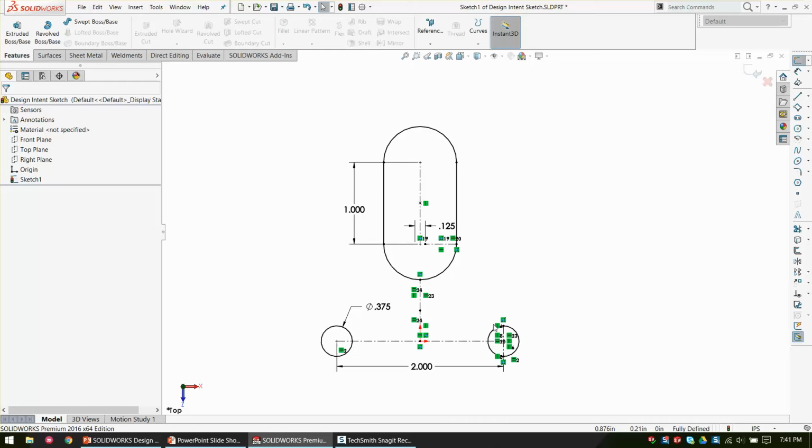So the configuration class is specifically talking about the same type of geometry, many different variations of it. In this particular instance, I might only want one variation, but I know for sure because I work for Steve, and Steve never, ever thinks the same thing day in and day out. I know for a fact Steve's going to come up to me tomorrow and say, those dimensions should change. But based on the design intent of what Steve and I talked about before, I know that if the diameter changes, that slot also has to change. So to keep Steve happy, to keep doing a good job, I can change one dimension, the entire sketch rebuilds. I don't need to maintain the old version. I don't need to configure this at all. The design is morphing and evolving as we go.